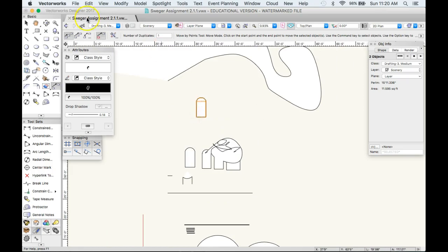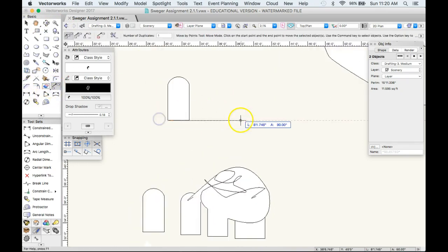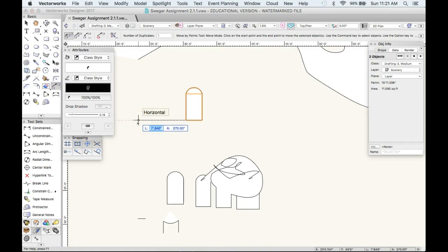I use this all the time. Also, don't forget to click that off if you just want to adjust a little bit. If you just want to move it over to the left a couple inches, I could click in this corner, hit the tab function, and say 1 foot, enter, enter, and it'll just move it over 1 foot, okay?